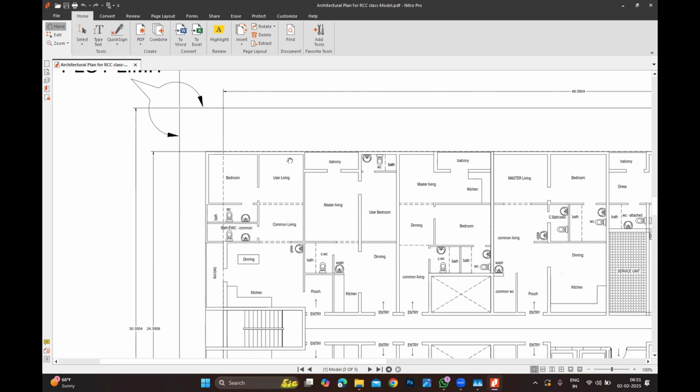You know what happens? Where the corridor is starting, adjacent to the flat washroom, there will be an opening adjacent to the small opening. And the column will fail in punching, and it is going to demand beams. When there is a beam, then you will have a problem with the MEP. When they are passing the AC duct, then you need to leave the opening. Understand?